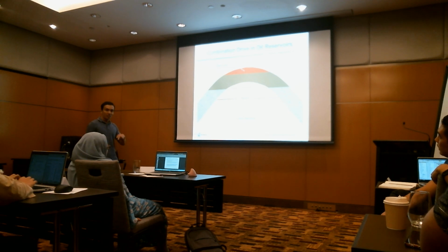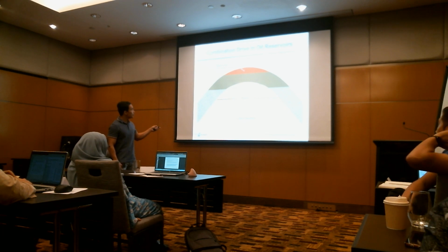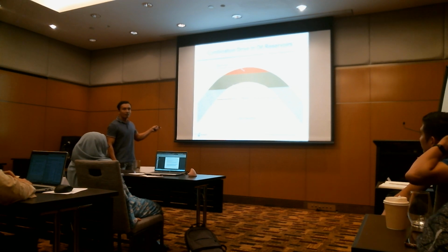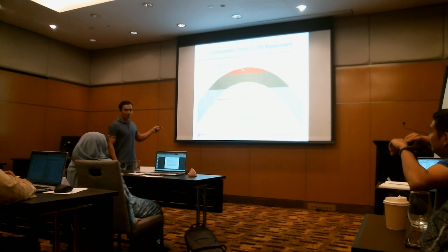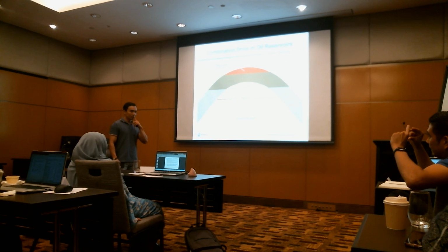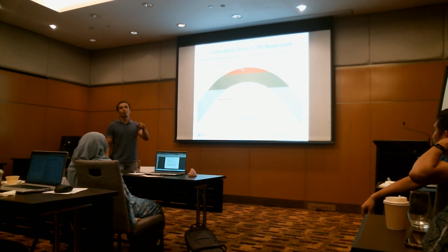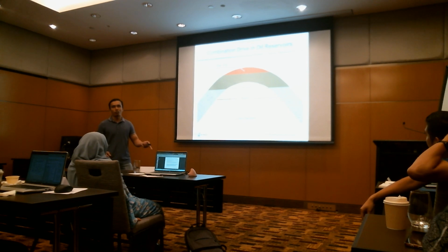Now, the next question is why you want to do that? GOR increases a lot. Because you can move your completion. If the oil moves up, then you are effectively not draining that rim. You want to maintain the rim as close to the well as possible. Yes, that's from the recovery point of view, to maximize or optimize.